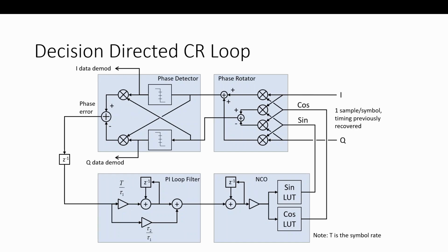And you're starting to see some of those structures we already explained. There's the phase rotator. There's that single multiplier, right? That same phase rotator or complex multiplier. We have I and Q coming in, and we multiply it by an IQ signal. It's shifting the carrier, and we'll have this phase detector, and then there's that loop filter. We'll have an error signal. There's the loop filter. It's going to float to what value it needs to be, and this is a numerically controlled oscillator. It's the digital equivalent of the VCO I showed you earlier. So we don't need to understand all that.